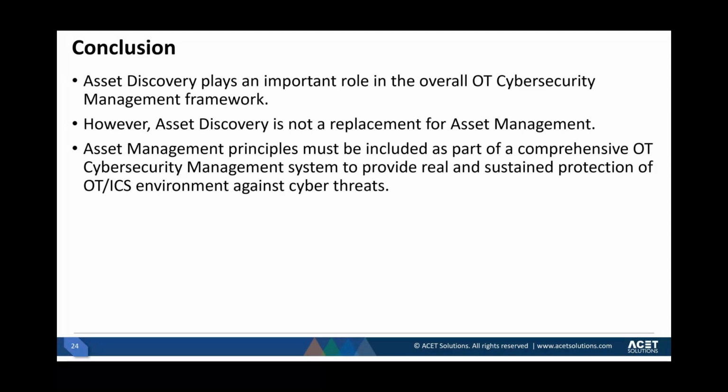There's one question that says, a new asset should be introduced into service as part of change management under asset management. Is it a correct assumption? Yes, and the way I understand, the process should be that, let's say you need to add a workstation to the control systems network, or you need to even replace a switch in a control systems network, an Ethernet switch. You should follow a change management process under the asset management regime.